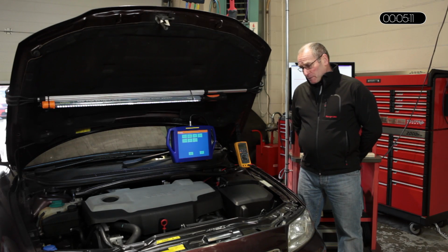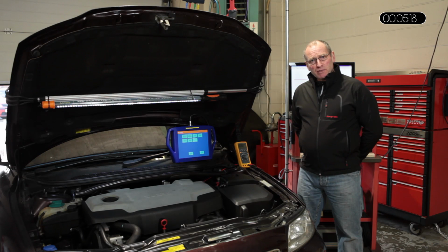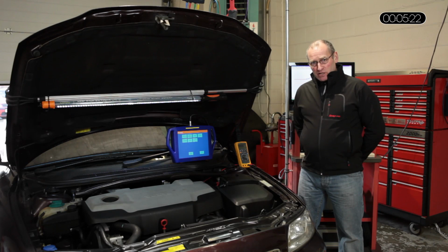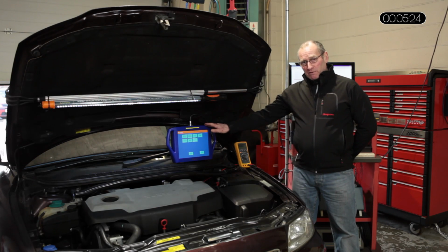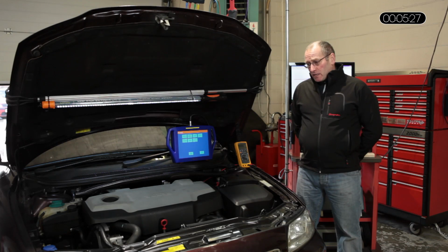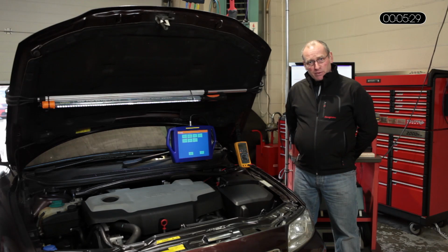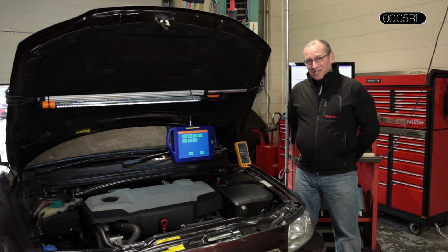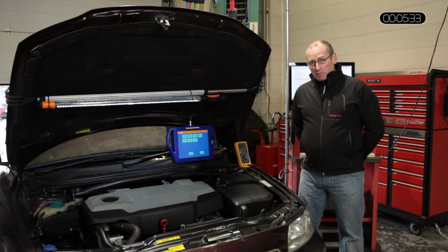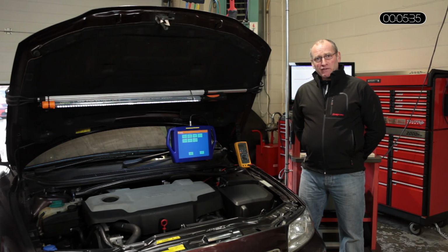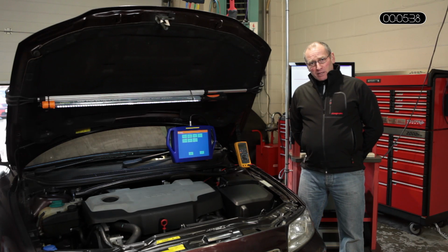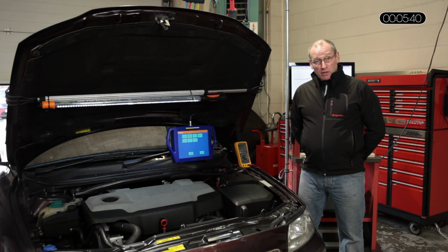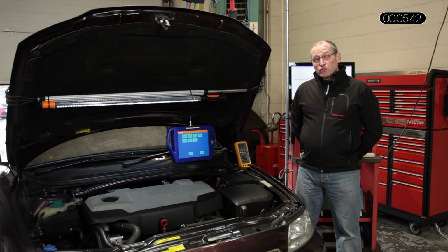We rectified the glow plugs. We carried out a thorough flushing procedure with the engine to clear any residual carbon, especially through the EGR valve. We then went through a manual regeneration process, which is done through the serial platform. We then re-examined the vehicle and drove it on the road. There was no change. The DPF still suggested a blockage, so the manual regeneration was a failure. There comes a point when the blockage is such that regeneration will not work. You are then faced with one of three possibilities.